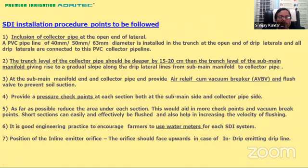As for the installation, the procedure generally followed by the farmers is this. You have to have a collector pipe at the end of the pipe. Typically, it could be a PVC or HDPE line of 40 or 50 millimeters. Then the trench level of the collector pipe should be deeper than that of the trench, because we want the water and any debris that is collected to get in. So you will have to keep it at a slightly lower level so that all the debris gets collected at the bottom. Then, as I already emphasized, the air release cum vacuum breaker valves at the required locations.